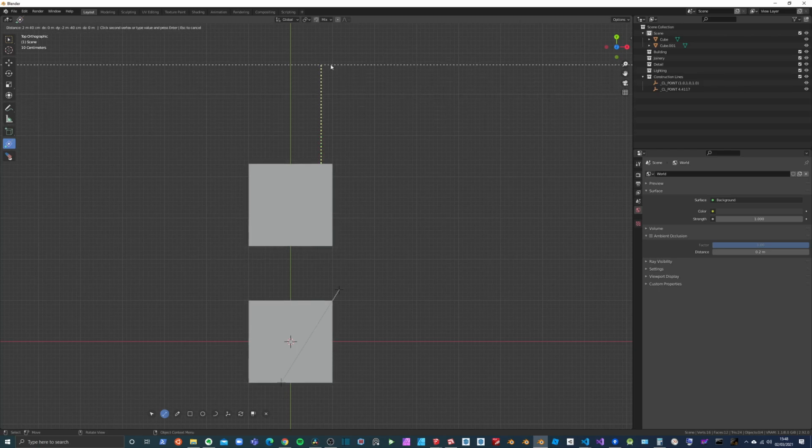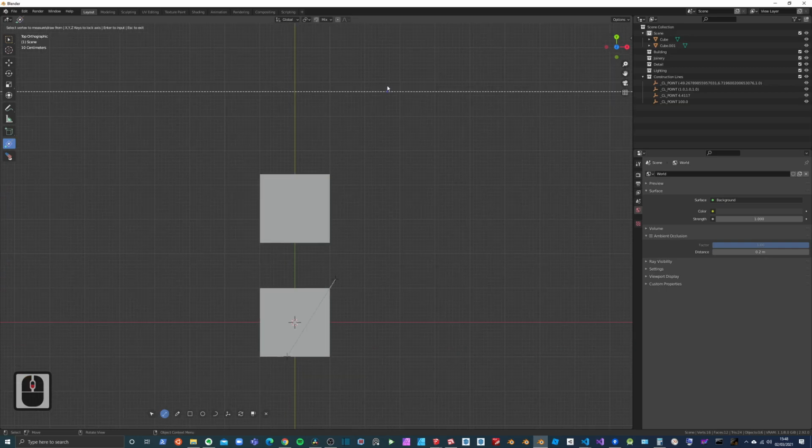And if I click just as normal, I now have a horizontal guide that I can snap to. And the same off of any edge, we can now have horizontal guides set. And what's really nice is that included now is, if guides intersect, you now have a snappable intersect point that we can work from. So you can now work from that point.